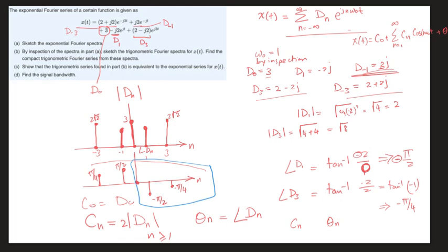And if you want to get the Cn, again, you take only the positive side of the magnitude. You keep the DC as is, because in the DC there is no factor of 2. The remaining ones are all scaled up by 2. You got the idea? So if we apply what I've just said, let me do it in a very small figure.